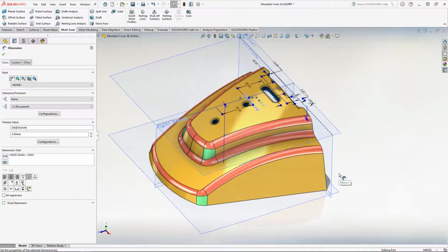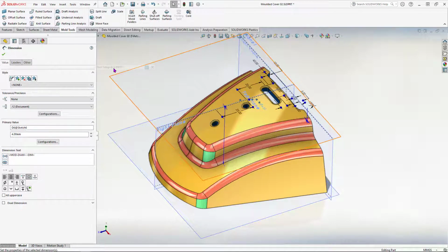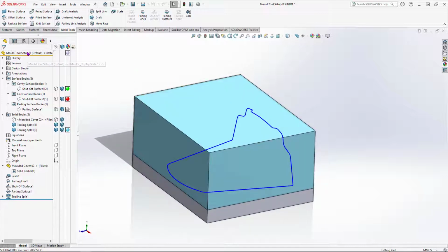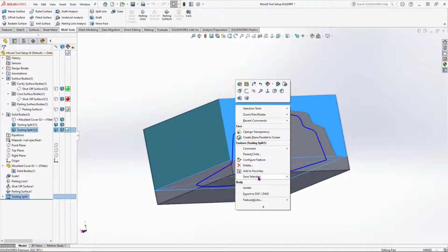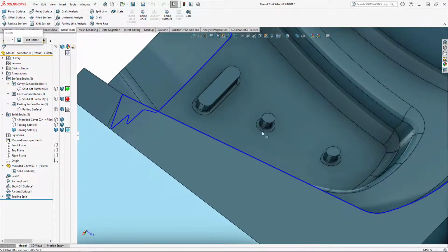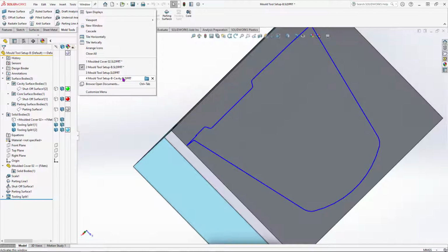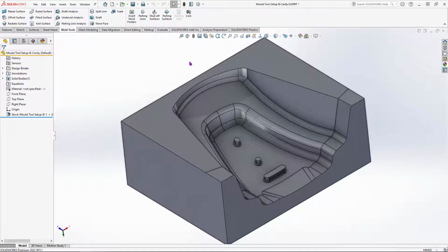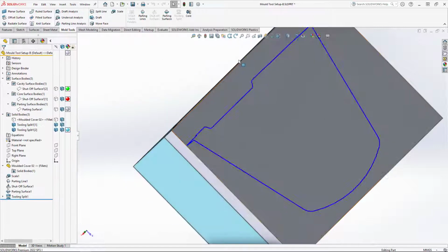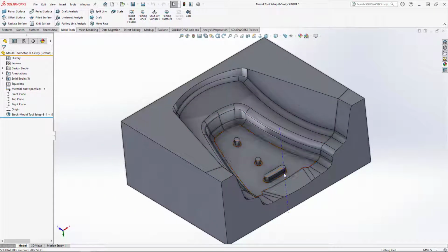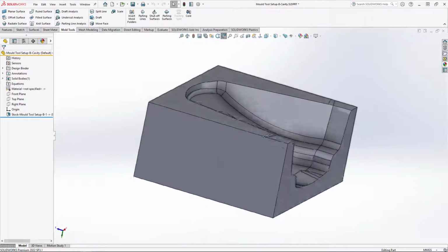And because the other two files are still open, if I now go into them, so I'm going into the mold assembly. It's not technically an assembly, it's a part. But if I now have a quick look to see, has this mold updated? Yes, it has. So you can see there, these little protrusions that stick out of this half of the mold have shrunk down because I made the change in the original part. And then if I go into the cavity, yes, so those changes flow all the way from the original part through our molding setup here, all the way into the final exported part here, which we could use for the basis of our CNC machining.